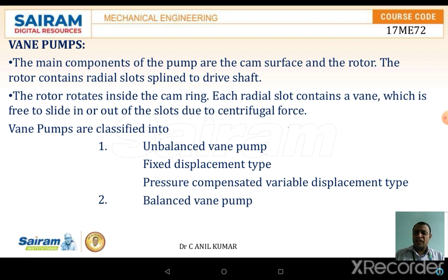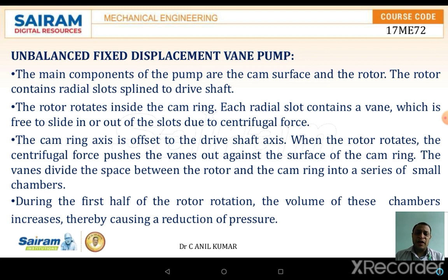The rotor rotates inside the cam ring, and each radial slot contains vanes, which freely slide in and out of the slots due to the centrifugal force created by the rotation of the shaft. The vane pumps are classified as unbalanced vane pumps as well as balanced vane pumps. The unbalanced vane pumps are classified as fixed displacement pumps as well as variable displacement pumps. The first topic we are discussing is the unbalanced fixed displacement vane